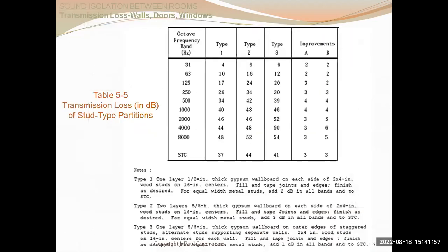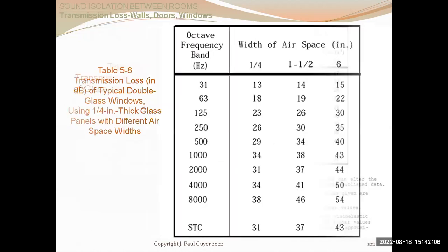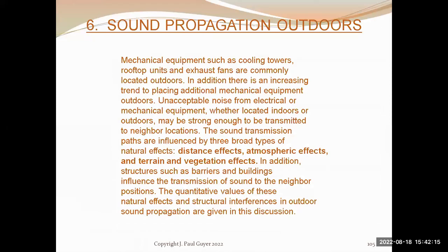There's a lot of tables here. Rather than getting into outdoor propagation, the things that you can do to improve the sound reducing characteristics of walls, barrier walls. One is to put fiberglass batts in the airspace between the studs. And that's because the airborne sound molecules impact on a microscopic scale the fibers of the fiberglass batts. The fibers deflect microscopically a certain amount, and in doing so absorb some of the acoustic energy of the air. So fiberglass batts are a good tool that you've got.